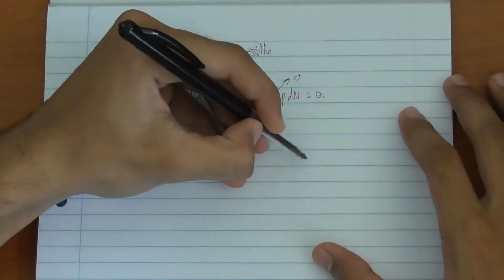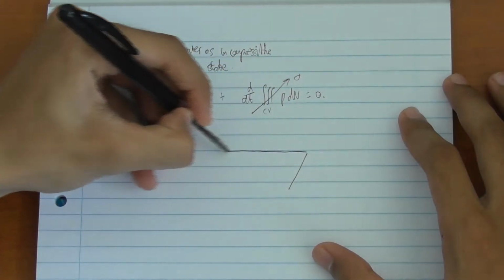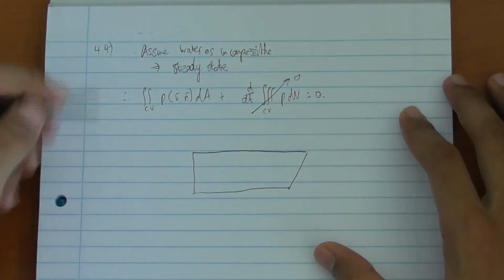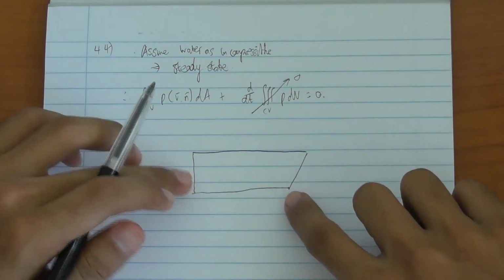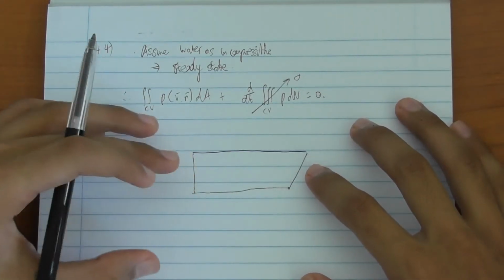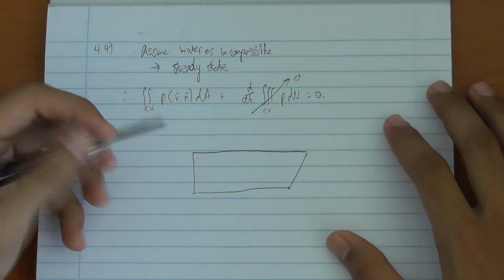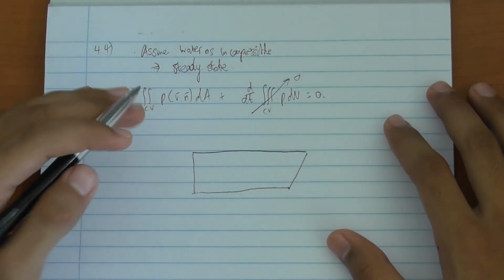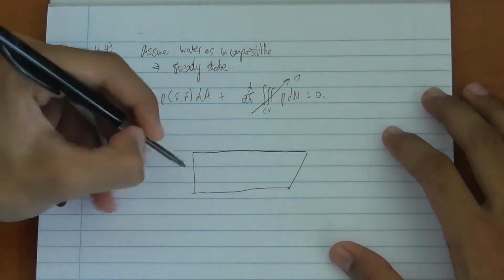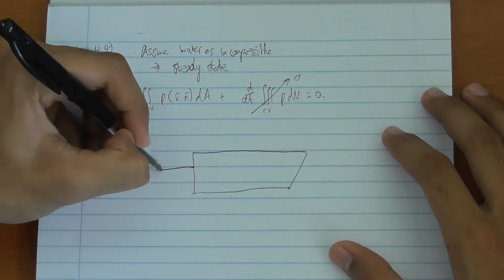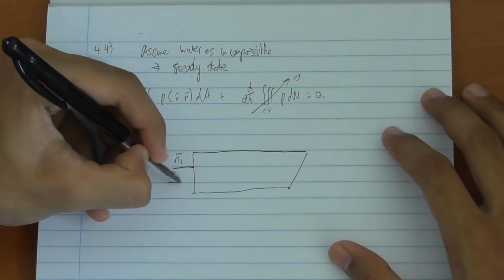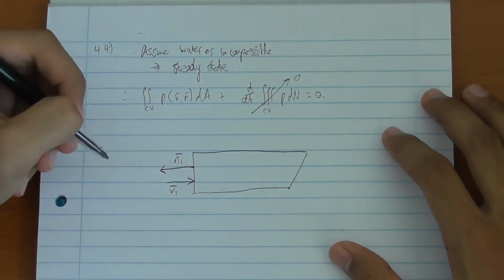So the channel looks a bit like this, with a straight entrance and a crooked exit. All right? It's not very neat, I tried my best. Okay, now you want to fill in your normal and your velocity vectors. So remember, your normal vector always points perpendicular to the control surface and away from the control surface. So perpendicular to and away from the control surface is normal 1. The velocity, the fluid is entering, so velocity is in this direction.